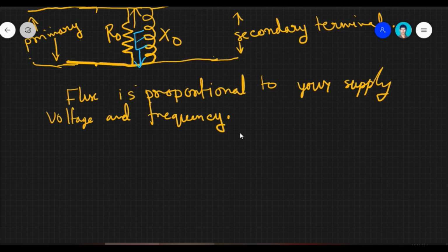Because only when we put a load across the secondary will we realize that the useful flux that primary can utilize, the secondary is getting deprived of. And more importantly, when you connect the secondary with a load, the secondary will produce its own flux to oppose the primary flux, and at that time also the secondary side flux will not link with your primary side flux.